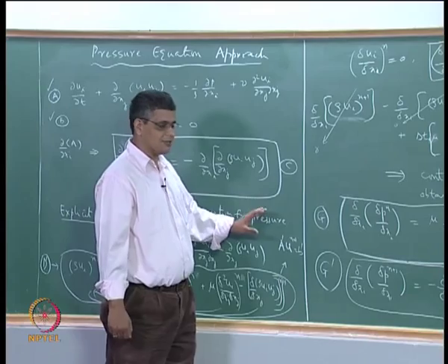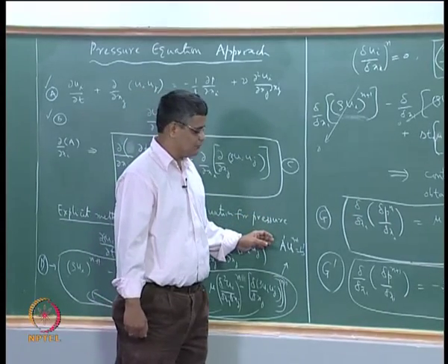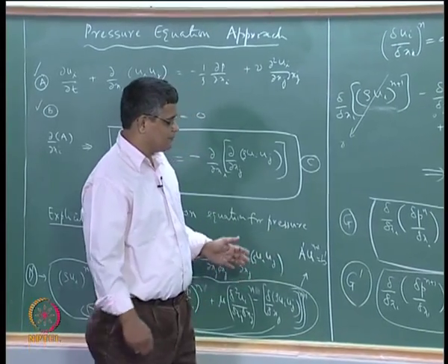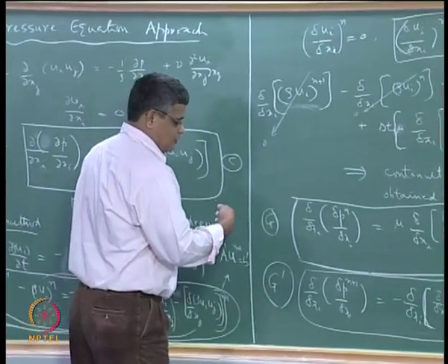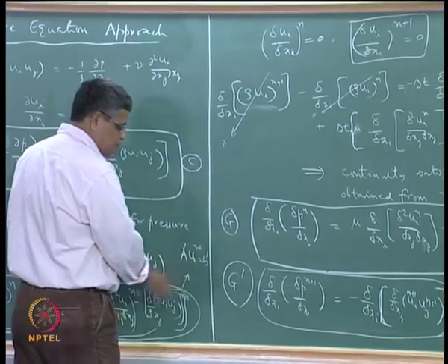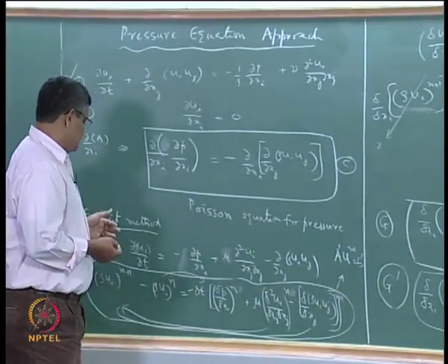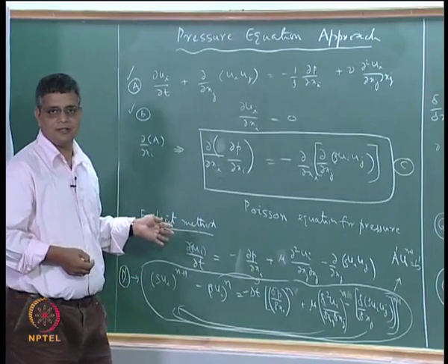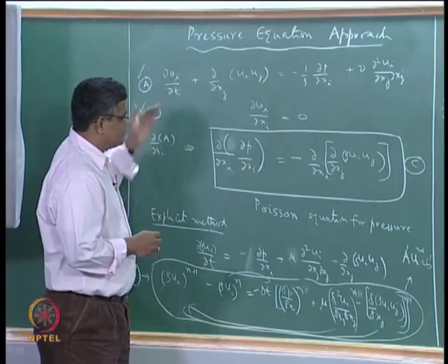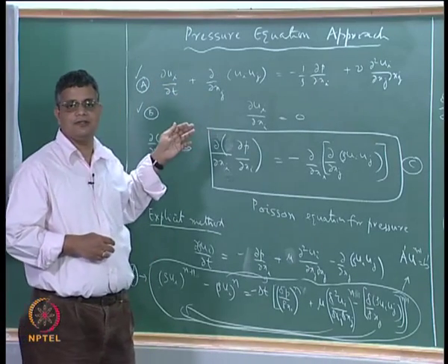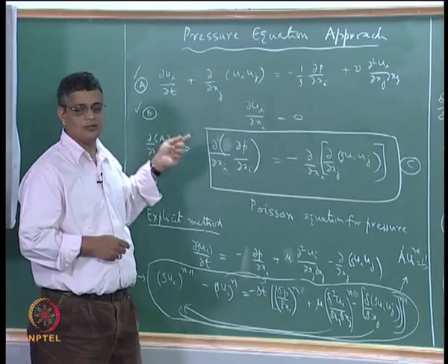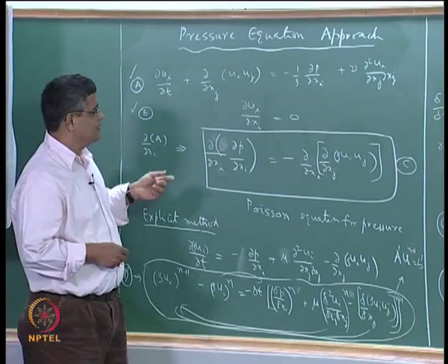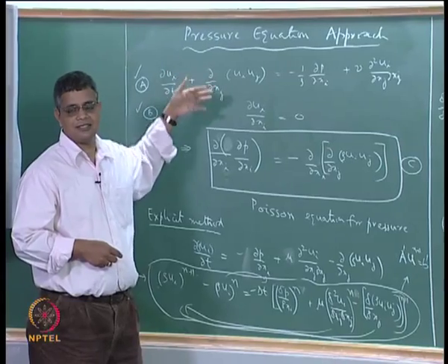So some methods which give us an efficient solution for repeated solution of Au equal to b cannot be used in this. Okay, so the overall effort that is needed to implement an implicit method is much more than in the case of explicit method, but the Navier-Stokes equations are coupled equations, in the sense that if you want to solve the x momentum equation, you also have to know V and W, and we also have this pressure business that is coming into picture.